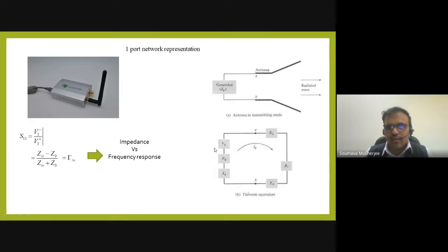So we will make a graph, and in that graph we can say that this antenna is working very precisely in some band. What is the band? The band where its input impedance matches the source side impedance. That is the case where whatever voltage wave or current wave we are giving gets accepted by the antenna, and almost a negligible amount is getting reflected.